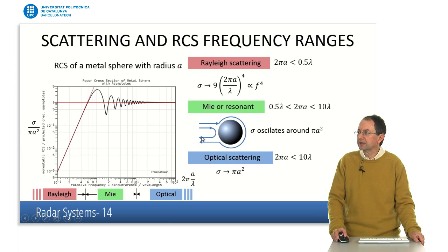We have a frontal mechanism and a traveling wave, a creeping wave, which propagates around the sphere and is vectorially, or phasorially, added to the frontal mechanism. This means that, depending on the phases of these 2 mechanisms, they are going to reinforce or tend to cancel each other. Actually, the creeping wave is not as strong as the frontal wave, so the cancellation is never total. And when we increase frequency, the traveling wave role decreases with respect to the frontal mechanism, which is going to be stronger or dominant. This means that the fluctuation drops up to a limit where we don't notice any variation.